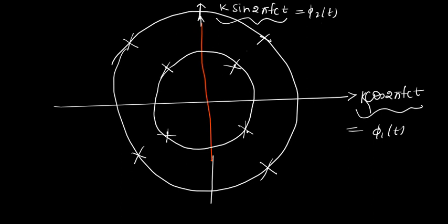As you can see, this will have same phase but different amplitude, this has same phase but different amplitude, this has same amplitude but different phase. So, this is how you can differentiate. QAM is a more general form of modulation scheme or constellation design, which is a combination of ASK and PSK. Now, have you understood?